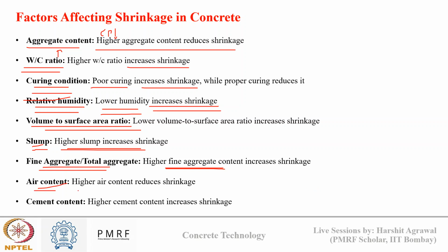Air content reduces shrinkage. Why? Because it provides a release of pressure. Okay, so it is like a stress relief point, like how we discussed in air entraining concrete. In air entraining concrete, what is happening? There is continuous expansion and contraction of water inside concrete. So when there are pores present inside concrete which are vacant, this expansion and contraction is relieved there. Okay, so the same thing applies here also.